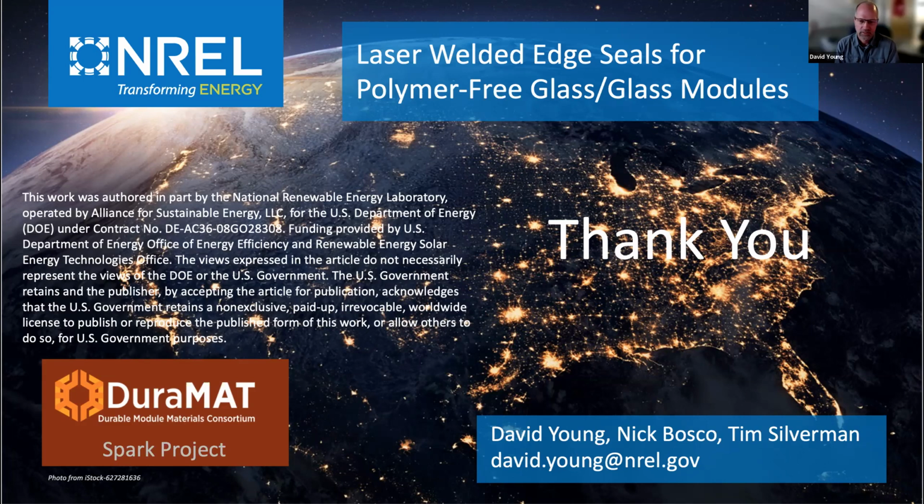Yeah, this would be in place of a laminator. So you'd be in that environment, and you probably want to have a clean room environment, at least a small clean room, at least around the tool, because you'd want to bring your glass right out of the cleaning and blow it off, make sure it doesn't have any particles on it, and then right into the laser welder. You really can't afford to have particles on the glass. And that may be a downfall of this project, of having to have clean glass over 1 meter by 2 meter areas could be tough.